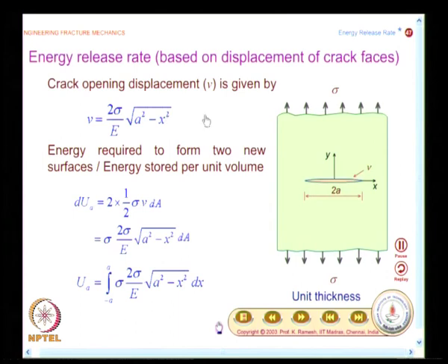That is the reason why I said in the class that when you have a single crack, extend it by a little and close it; that is the best way to identify the interrelationship between K and G. Finding the energy release using this crack face displacement was only a historical note, and you can actually put a horizontal stress component here, the result is valid, and the ultimate interrelationship between G and K still remains the same.